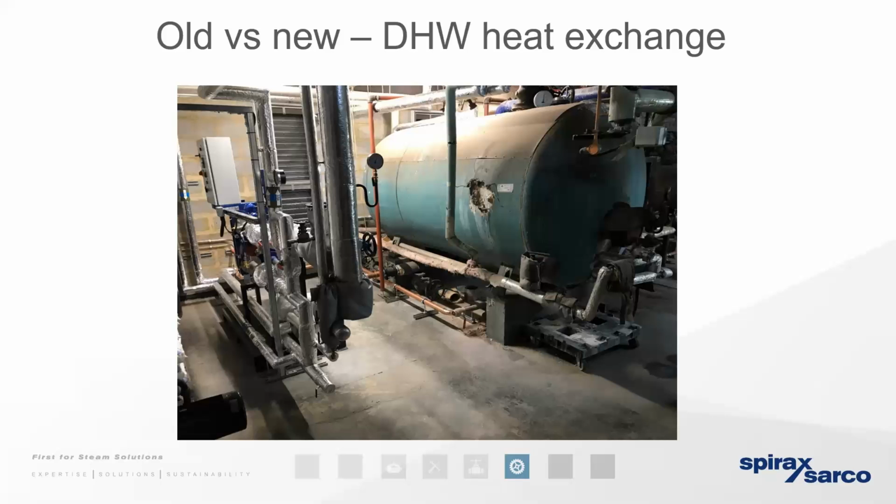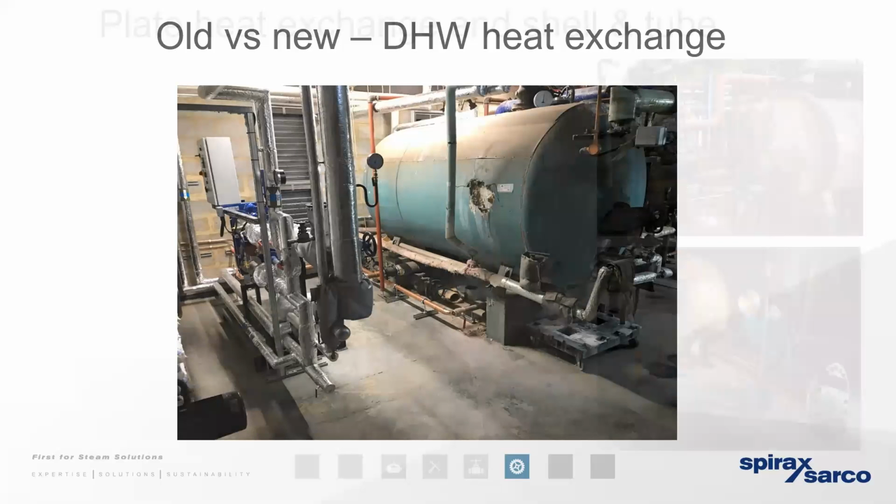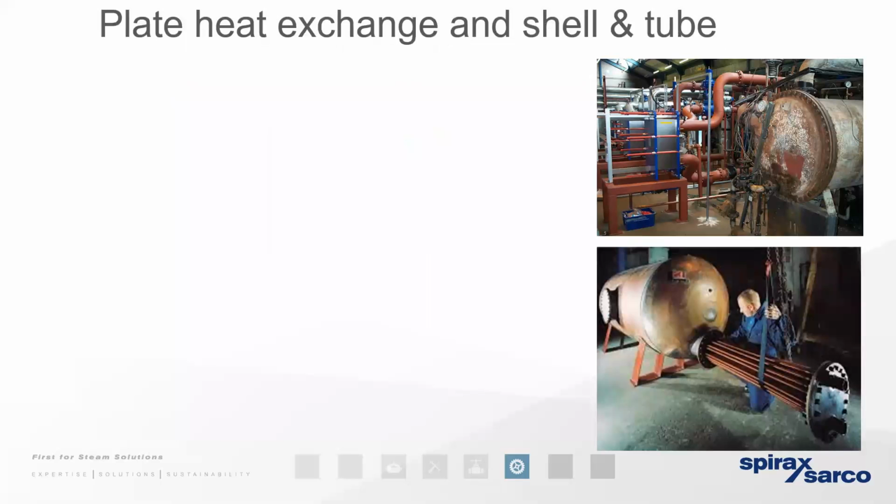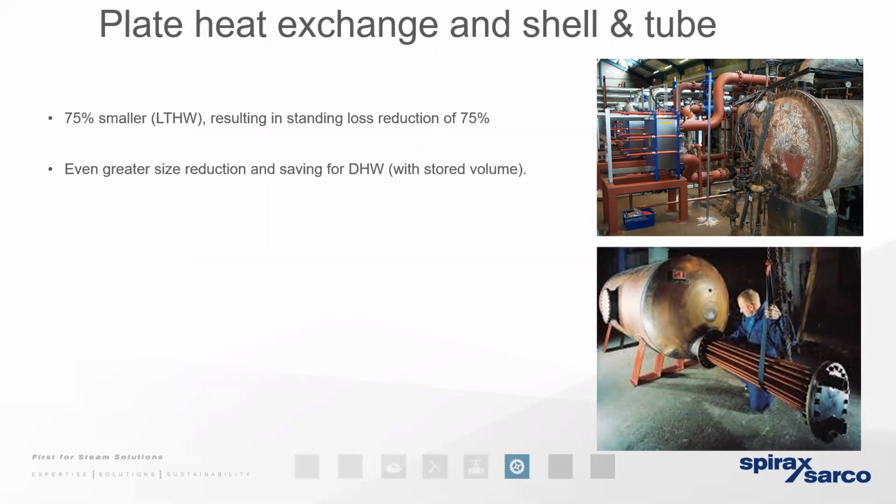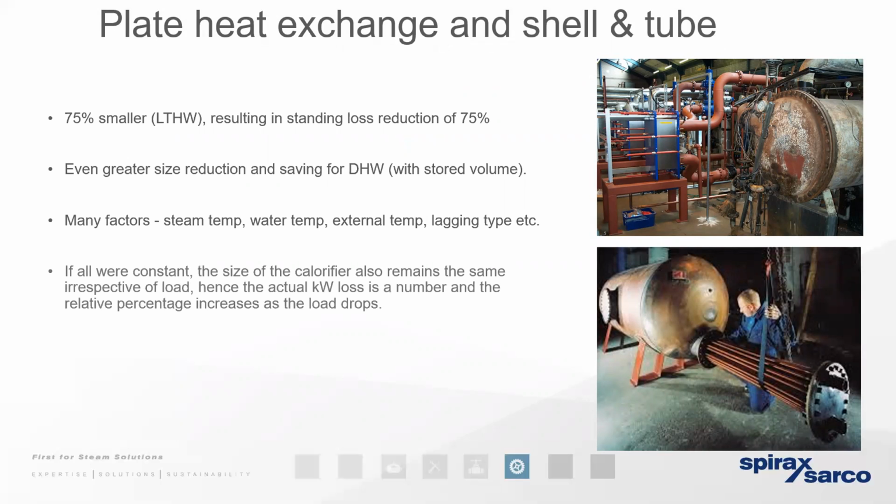And of course, if we're holding hot water in storage, we've got that Pressure Equipment Directive and the Legionella L8 issue to contend with. On the subject of manual handling, if we've got to take the heat exchanger apart periodically for insurance inspections and for descaling, we're going to need lifting tackle in the plant room. We're going to need an additional footprint of space around the heat exchanger to allow us to do that. And that's on top of all the benefits that we have by moving towards an instantaneous system that can generate hot water from steam on demand.